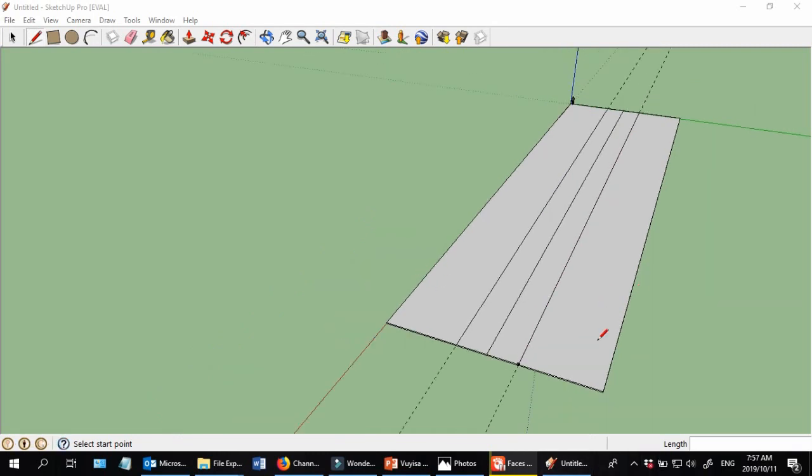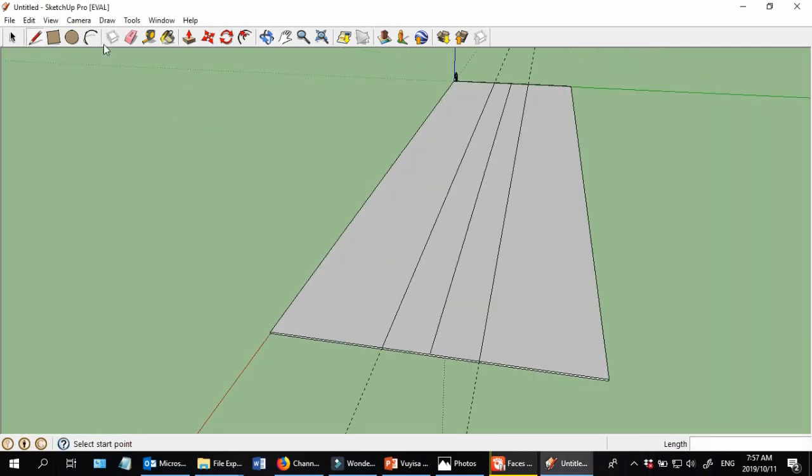All right, so we've drawn the lanes. On either side there's parking, so there's another 3 meters for parking. Again, you just type in 3 after you've got your tape measure tool, and then I draw these in. So with that done, the sidewalk appears automatically on the other side, but we want to also draw some buildings.